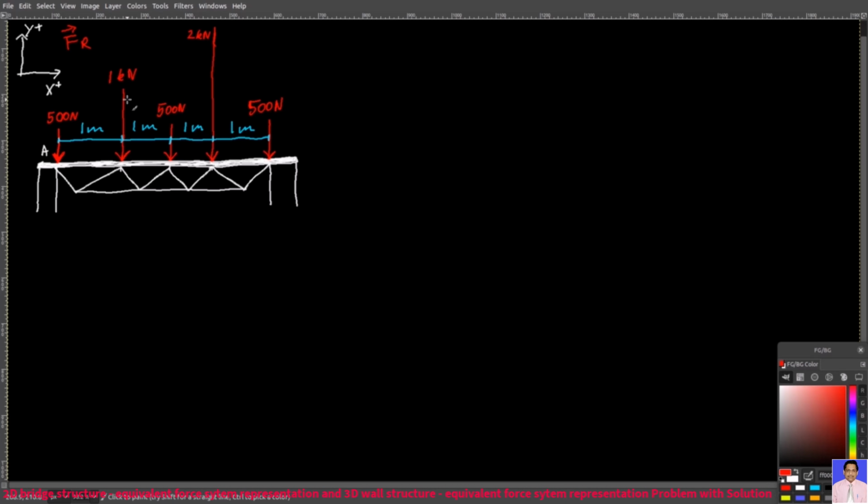Thank you very much. Welcome back. So let's figure out if we can replace this force system with a resultant force only without a couple moment. Let's first find this resultant force. It will be Fr equals all this times J. All these forces point down in the negative y direction.